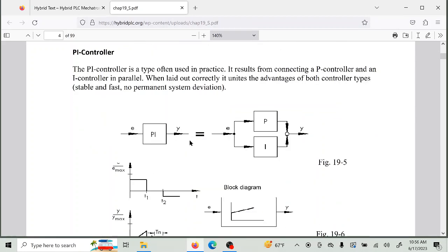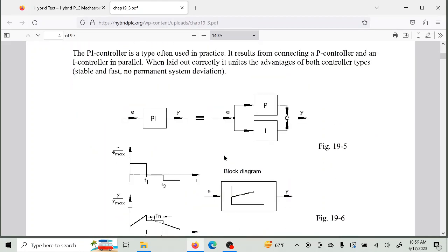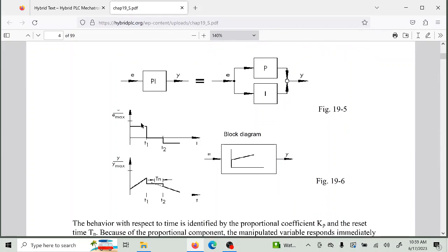Down here is the proportional and integral controller set up in the controller. This is the P and the I. Putting the two together, we have an error, and over time, from a baseline, it goes up, and then when it goes to 0, we have the proportional term coming down, and then it goes down again, because the proportional term is just a number times the error.